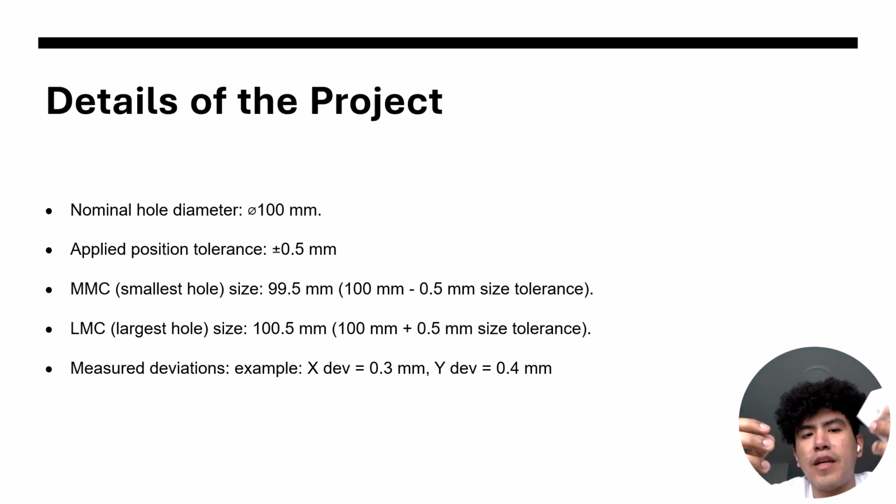If I want to apply LMC, in this situation I need to add 0.5 of size tolerance. So for the purpose of this project, I put measured deviations of 0.3 millimeters for the X axis and 0.4 for the Y axis.